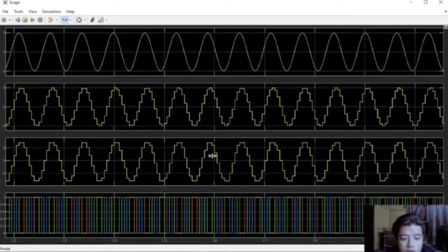The third waveform is the sampled signal, which also peaks at 5. We can see that the waveform has been distorted significantly, and the amplitude of the signal has increased after we have quantized the signal. And lastly is the encoded signal, which has been encoded in 4-bit PCM data format.